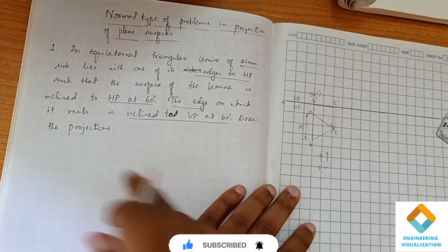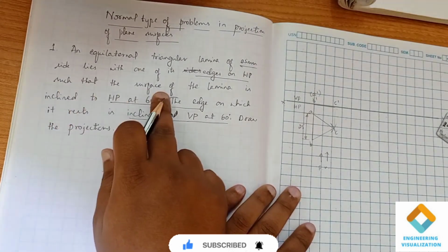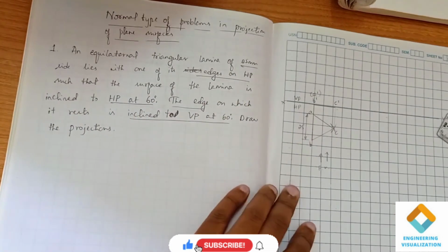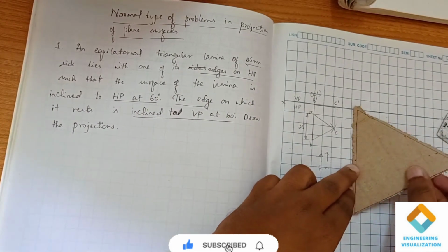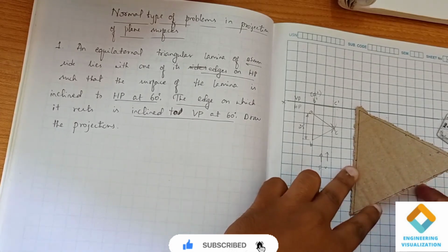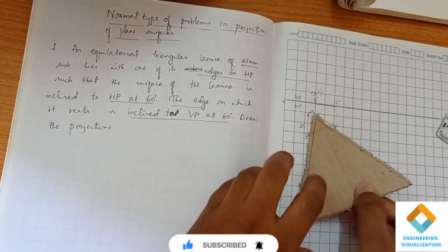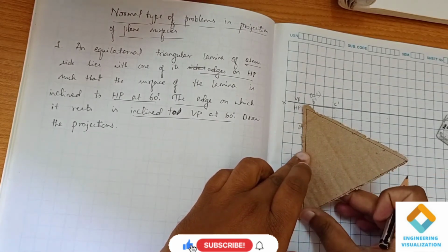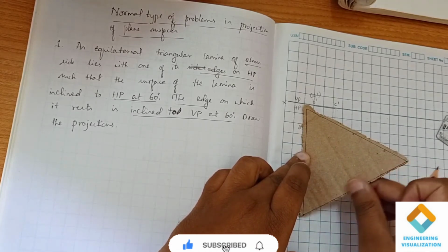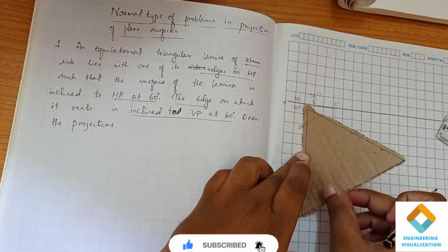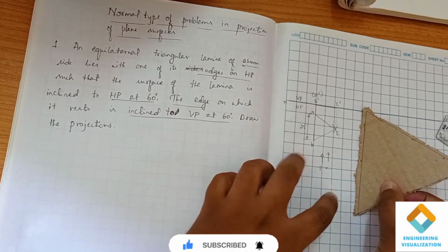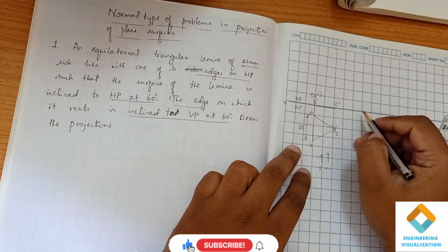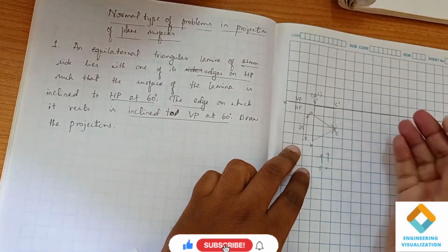Now you see the question, such that the surface of the lamina is inclined to HP at 60 degrees. So what we have to do here is, in the second position, incline this with respect to the HP plane by 60 degrees. We are inclining the edge B dash C dash, so the length B dash C dash will be inclined here. We are inclining only this edge BC. So in the front view I am going to incline this line by 60 degrees, and that is what we can see in the front view.